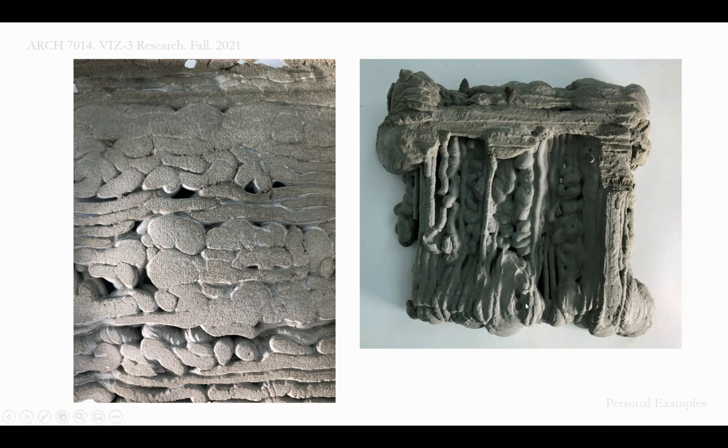So then here, I also did this again, but with a different material or medium, which was concrete. And here the exercise was playing with the extrusion. I kept the speed the same. So actually, I manipulated my G-code. So at certain points, it would release a little bit of material, which you can see here, which are these really stringy pieces. But then at certain points, I had it extrude a whole lot of material really quickly. And that's where you get these super huge blobs.